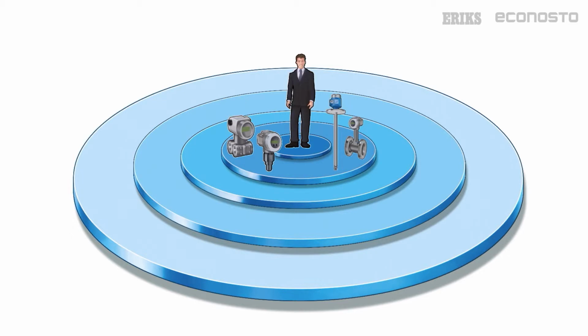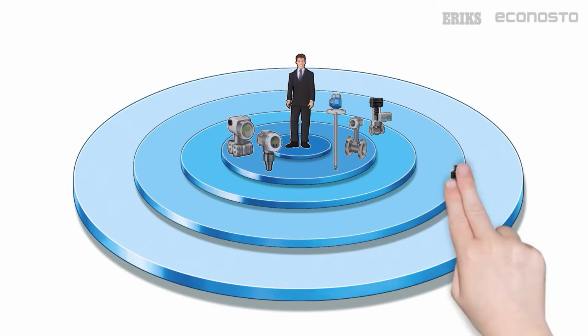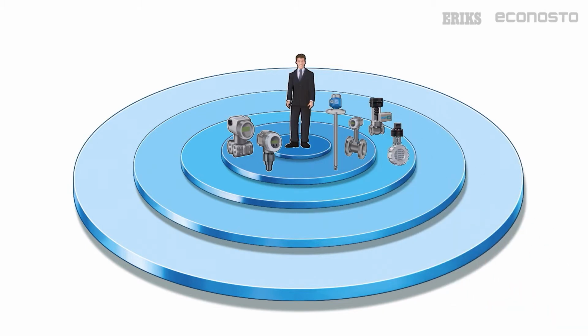You want to measure pressure, temperature, level, and flow and analysis. You need sensors for this. With regulating valves, you can control a process or a flow, and therefore the temperature as well, for example. But you can also close something off in this way. Imagine a vessel is full. At that point, you want to close off a pipeline with an open-close valve. And to have valves react and to know their position, you want to be able to activate them. You also want to be able to control them.